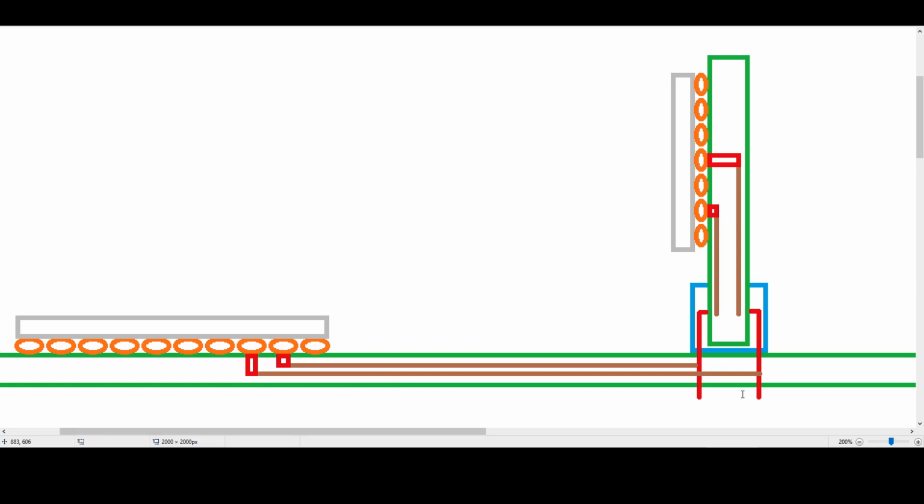These will go through the board. So now we have a loose end of metal sticking off the back of the board where the pins of the memory module go through. The memory module has to have the pads, and the pads will have contacts in the slot that have to make contact with the pads on our module, and these contacts won't have optimal shapes because they have to be springs.